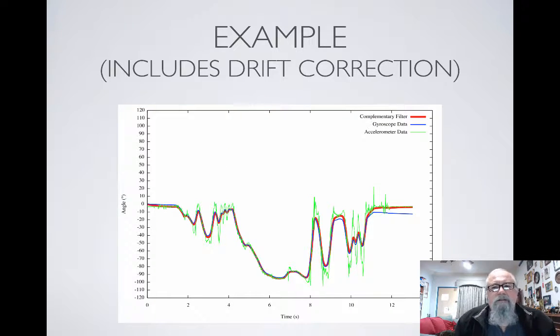The other things we need to look at, and this is where things become very, very complex, is conditioning the signal to suit our application. Now, not only do we have to look at removing high frequency or low frequency noise, depending on our application, through either a high pass or low pass filter, there are other types of filters which enable us to reduce errors within the sensors themselves. Now, this is an example of an inertial measurement unit that we're using in gait analysis. Not only does it have high frequency components which can interfere with our signal and the processing of our data,